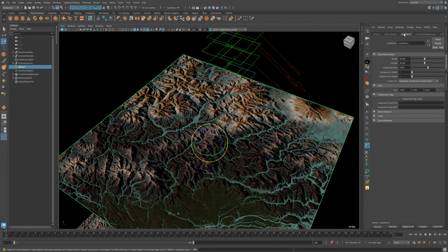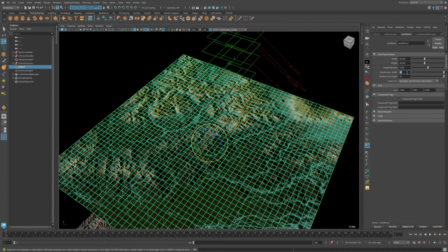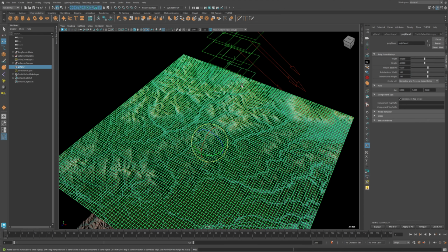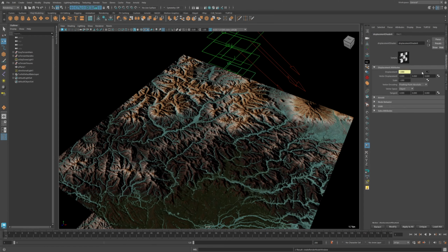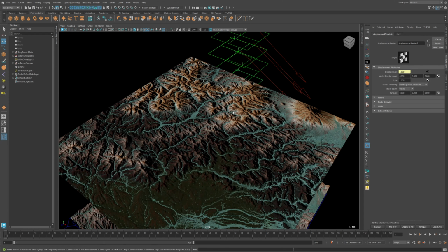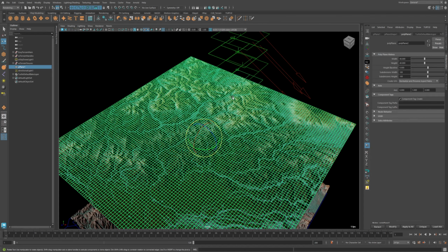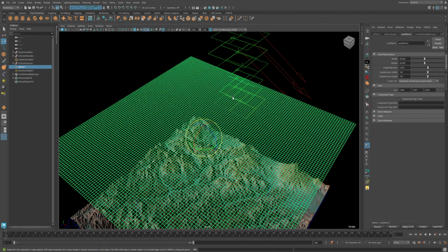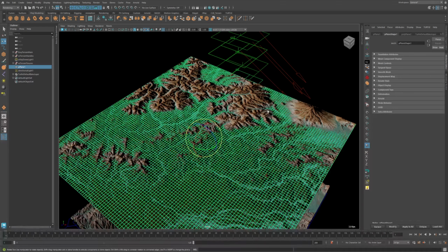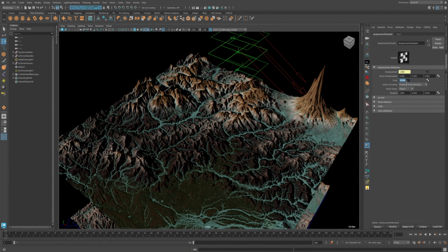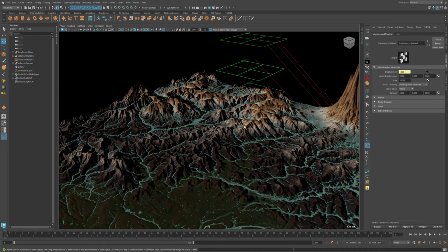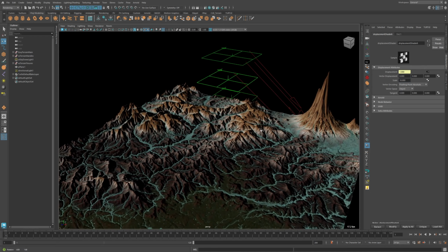And for the displacement map, I'm not sure if Maya is a good place to test it, but let's try it. Let's go and assign the height map. To see the displacement over this surface, just select it and hit Alt plus 3, just the way you hit 3 and it gives you the smooth mesh. Now just hold Alt and it will show displacement. Let's increase it a little bit. And you can see we have the displacement as well.